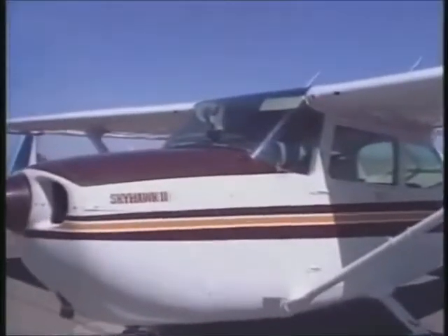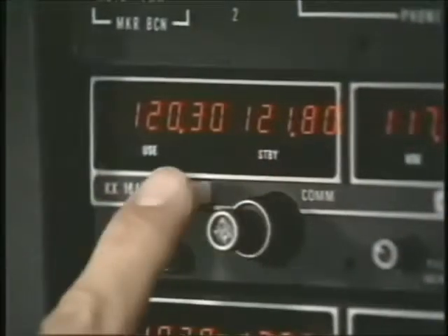When you contact ground control at an airport that does not have a clearance delivery but provides radar services to VFR pilots, you should include the direction of flight or your destination. In this situation, the ground controller will give you a transponder code and departure frequency.